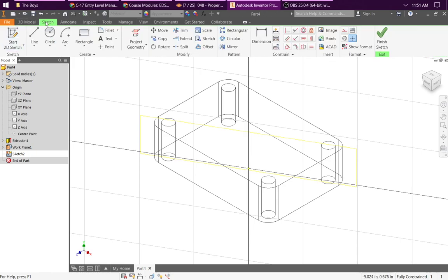And I'm going to go back into the sketch tab. I'm going to project the back edge onto this view. That just makes it so that we can see that line easily when we're trying to sketch. And then I'm going to get out of the project geometry. I just hit escape. Then I don't really want to draw it in this view. Again, like I said, I like to draw it where I'm looking flat on, but our view cube doesn't really give us an option for looking directly at a plane we just created.